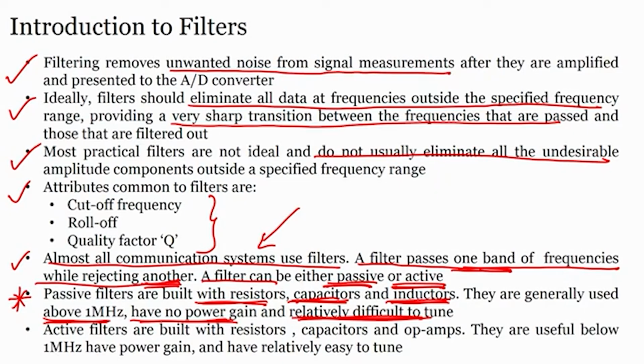No power gain because there is no op amp, no transistors, no active components and there is no feedback, so we cannot change the gain, there is no power gain. It is difficult to tune and generally they are not used at extremely low frequency, right. Now, active filters are built with resistors,